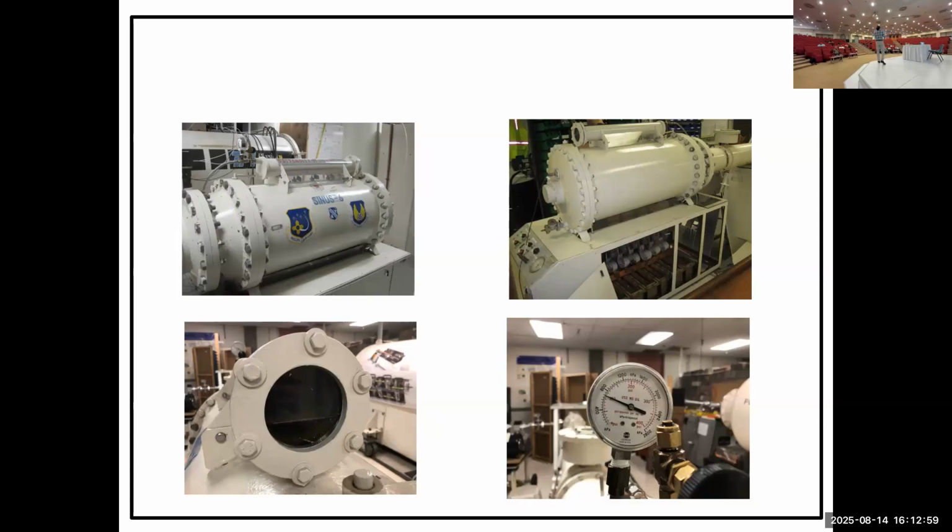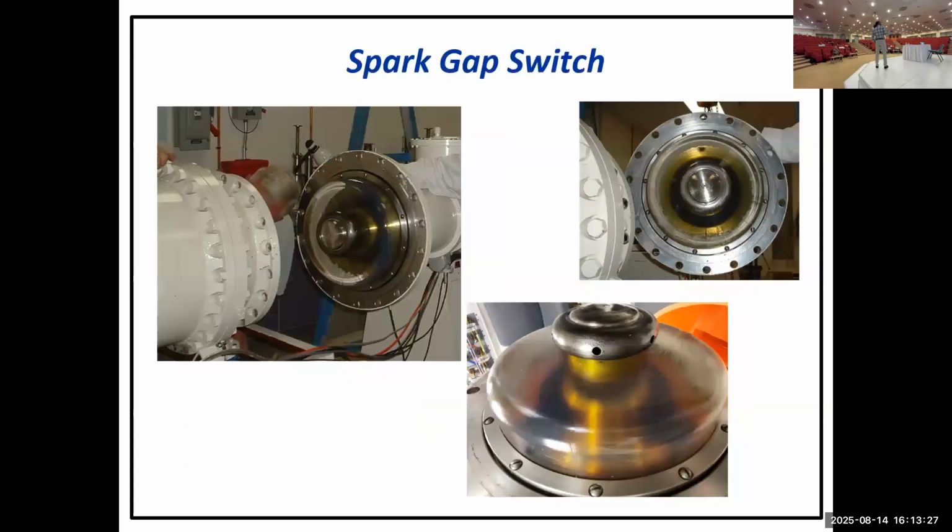So we had a student who reduced the pressure to atmospheric on Friday, and he went home. For some reason he was changing something and reduced it close to atmospheric pressure, and the PI came Monday morning and found all the oil leaking. The system expanded, and the oil was leaking, and it came to the spark gap. So we had to open it to clean it, and we cleaned the oil here, put it back, and it worked just fine.